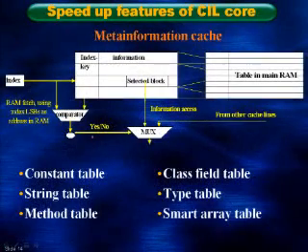But instead of DSP, a CIL instruction is 1 byte in size, or 2 bytes for extended instructions, and may have 1 byte or 4 byte parameters. And the DSP prefetch unit is extended with the CIL instruction buffer, and the CIL processor has Harvard architecture with separated data memory and program code memory spaces.